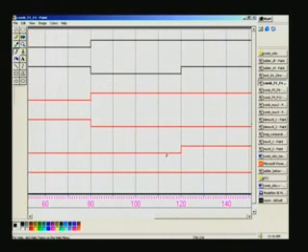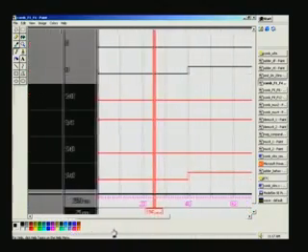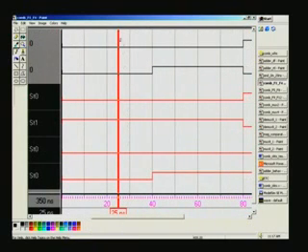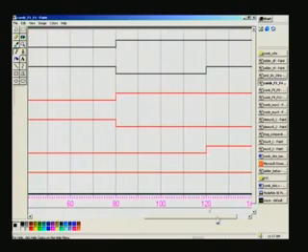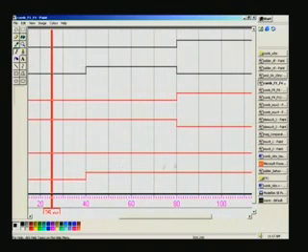And now up to this it is the same, 1 0, this 1 0 here, and now here it is 1 1. So at precisely that point of time it goes high here. So this is the AND gate, and similarly the OR gate. The OR gate is F4, OR of A and B. So again 0 plus 0 is 0 here, and then 0 plus 1 is 1 here, and it continues to be 1 because 0 1, 1 0, or 1 1 all basically give a 1 result. So it continues to be 1 from there. So we have seen the functionality of the first four outputs.